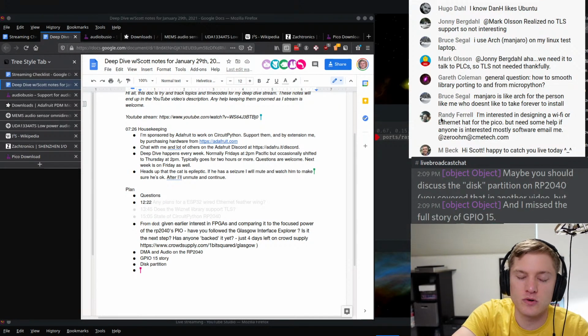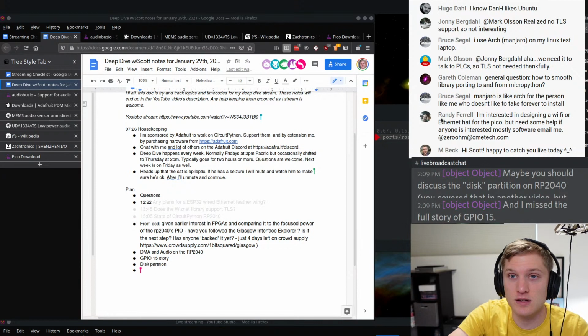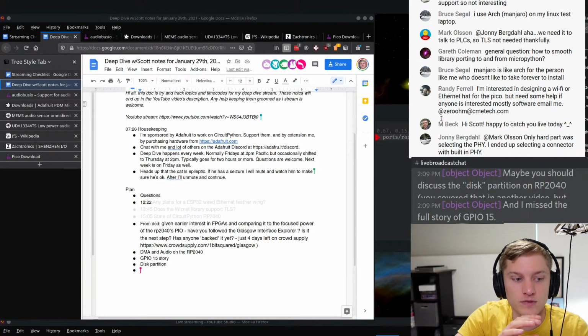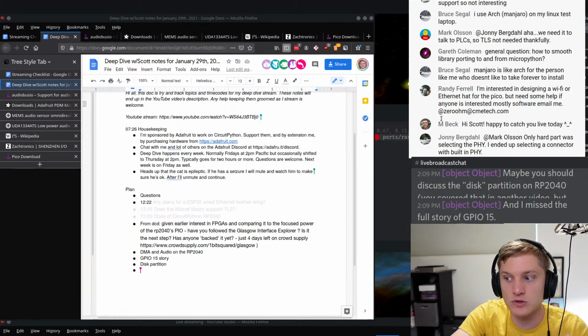And then there's a big question mark also about how to do async buffers to and from a PIO that I've been thinking a lot about. But my current focus is actually on all the audio stuff. So I want to do audio PWM, so playback audio to the PWM on the RP2040. I want to do I2S out as well, which will give you better quality.